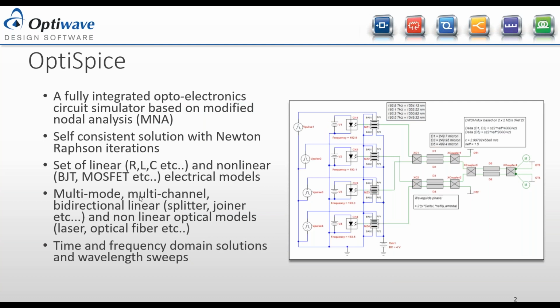So let's start talking about SPICE. Our OptiSPICE is based on standard Berkeley SPICE, which is commonly used for electrical analog simulation. What Berkeley SPICE does is it takes equations describing basic components, and also how these components are related to each other, and it puts them in a system matrix and solves them simultaneously. It can do either transient simulation or operating point or AC simulation.